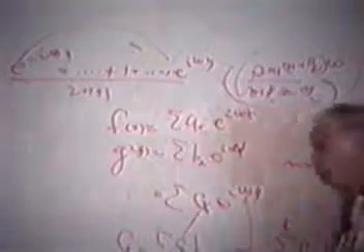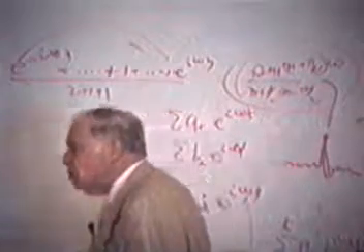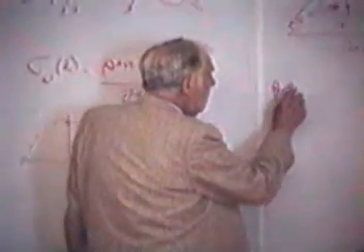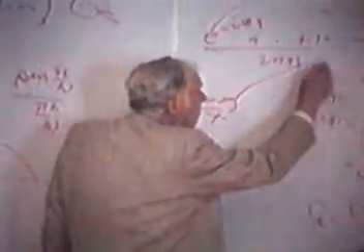Now, whether I sample first and get this, or whether I first cut it on and off and then do the sampling, it'll turn out to be the same. Because when I do the continuous one, I get a sine x over x form, and when I sum it over all the aliasing, this becomes that kind of a term. So there's no difference whether I think of first looking at the continuous signal, cutting on and off, and then sampling, or whether I sample and cut it on or off. It makes no difference. I get the same result, the same smearing of every single thing.